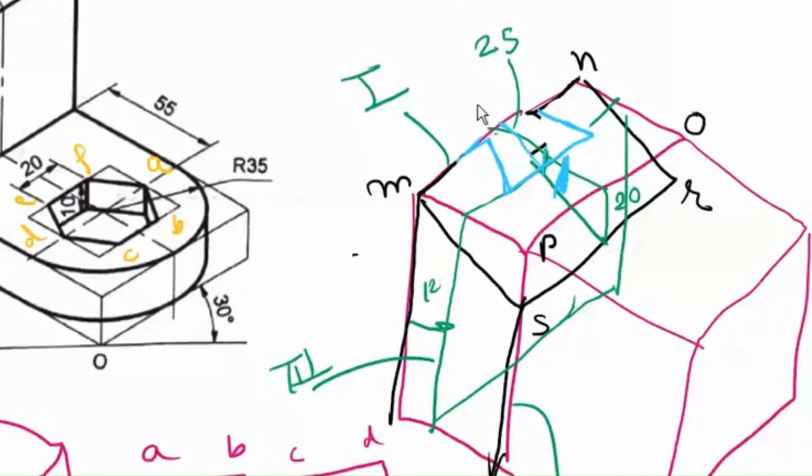ओके, इसके बाद में यहाँ से 12 mm, ये 12 mm का जो प्लेन है, वहां से drop a line perpendicular on this inclined line. So you get this point. Which point? You will get this point. And on this point you have to draw the slot.